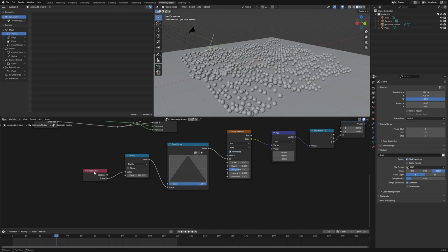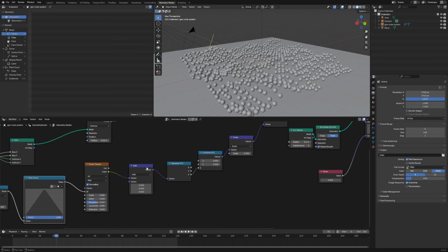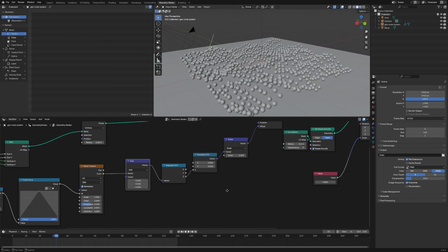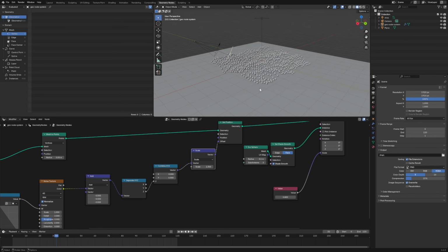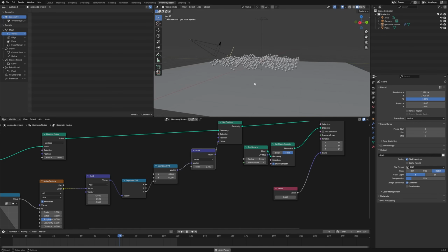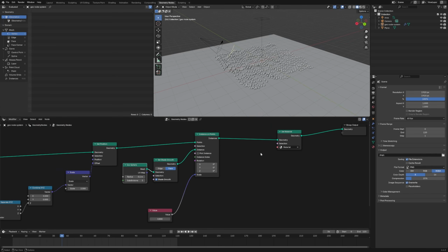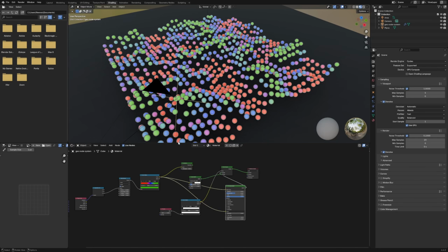We were able to animate it using scene time and dividing it in a float curve, so it loops perfectly. We offset the noise by -0.5, and then we were able to set it with a combine XYZ in order to make sure we only had it moving up on the Z component. And we also scaled the noise a little bit to make sure it went higher up. That's what I decided to do at the very end, make the noise scale a bit bigger. We were able to use Ico Spheres, set them smooth, and use the shading editor.